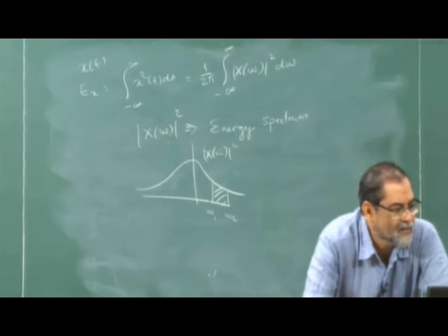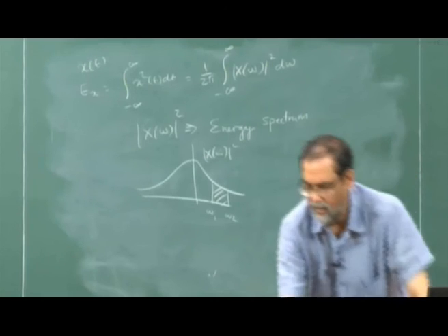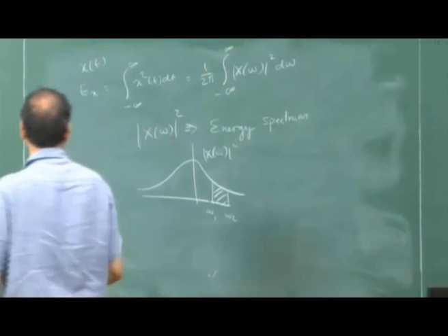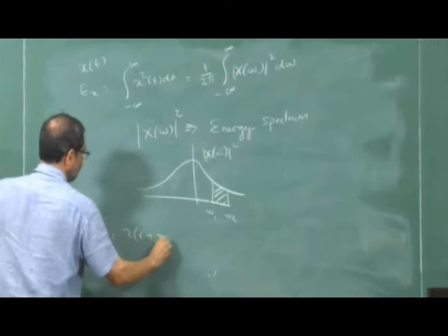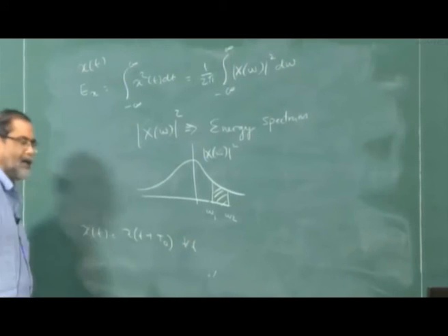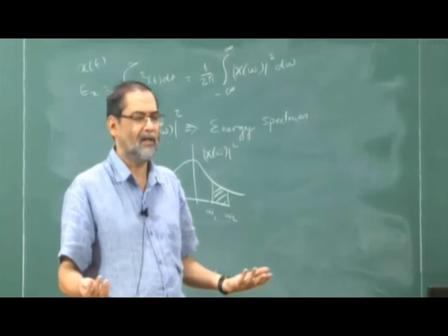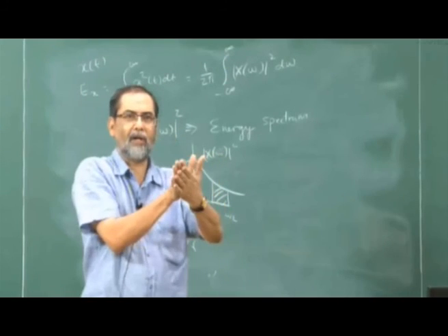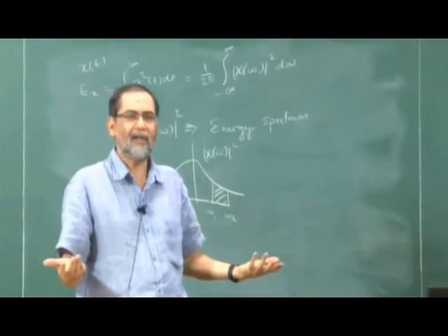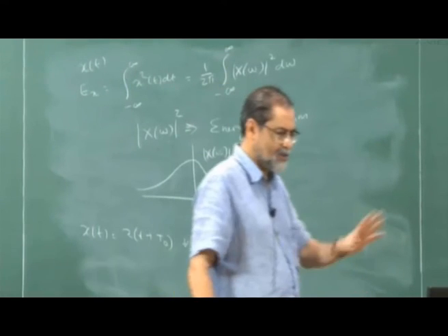If two LTI systems are cascaded, then the impulse response is convolved. Okay, fine. How is the periodicity of a signal calculated? We define periodicity by simply saying that x of t is equal to x of t plus t naught for all t, meaning a signal and its shifted versions look identical when you shift it by t naught. The smallest value of t naught is called the period. You take a sinusoid, shift it by one period, and it looks the same. If a signal and its shifted versions look identical, then it is periodic. That's our simple definition of periodicity.